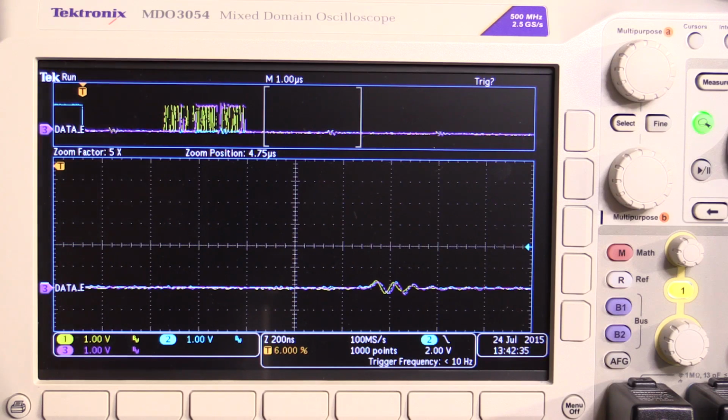Now, obviously, 20 megahertz doesn't actually mean squat if the delays between each data packet, which is the 24 bits, take 60, 70 microseconds before you're even able to remotely try and output your next byte again. It just isn't going to cut it.